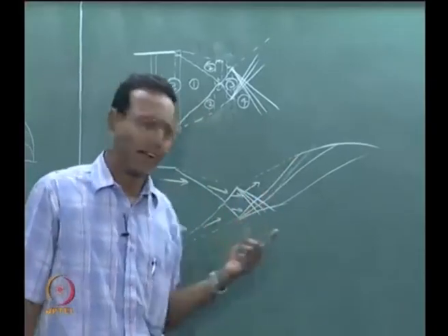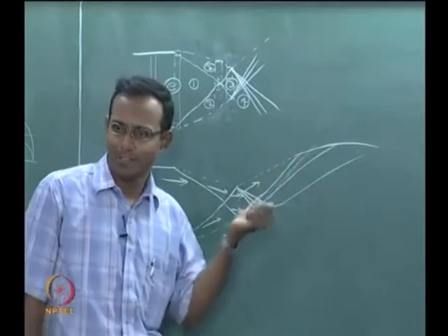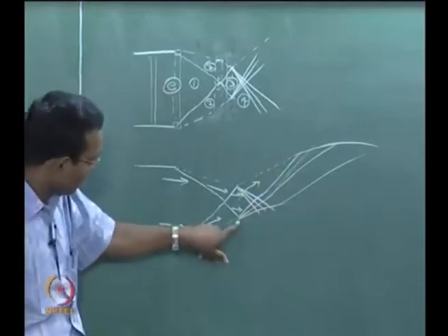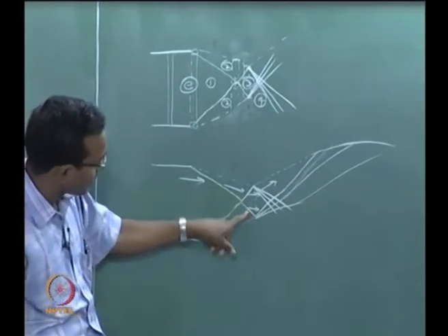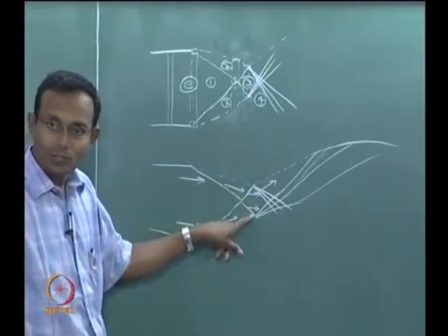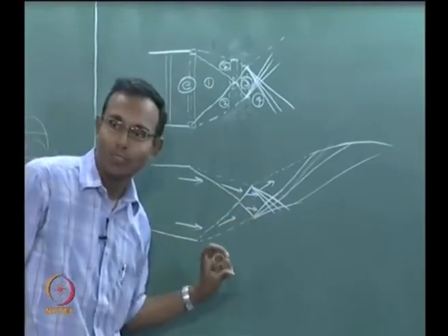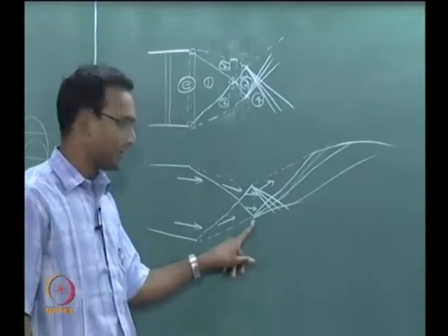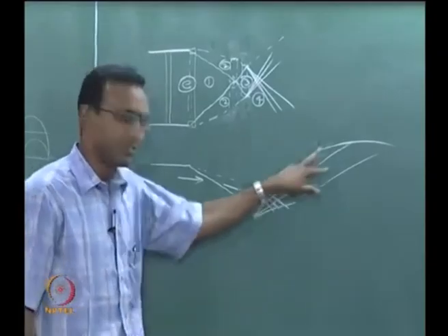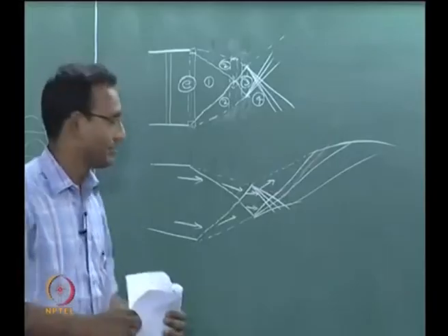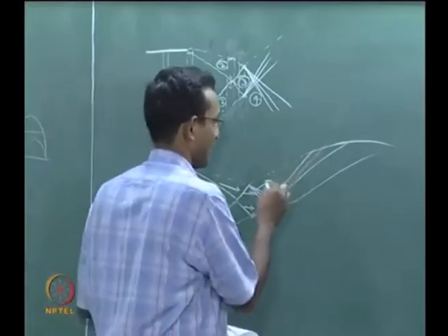It is just one wave, one expansion wave going, it needs to be replaced with one compression wave, while here there was a whole bunch of compression waves together coming as a shock. So they all have to be replaced by a whole bunch of expansion waves together at that point, and they are all running at different speeds, so they are separating out. Okay. That is a way of thinking about it.